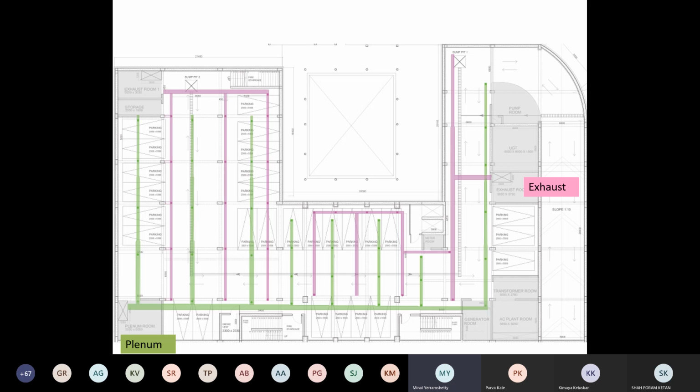Now the exhaust will not have that kind of power to pull all those layers of carbon monoxide fumes up. So what you will have to do is, at strategic points where there is parking only, you don't have to go around doing this everywhere, but where there is parking, because understand guys, monoxide is very heavy. It tends to settle down. So what you need to do is strategically, where you have the car parking, between two parking, between three parking, you need to take down.